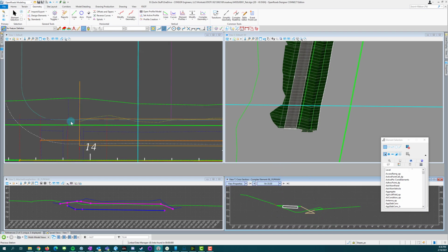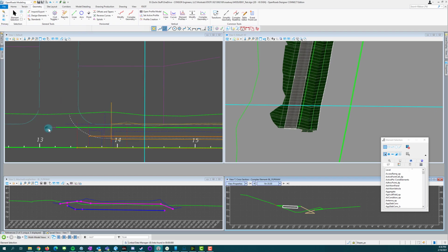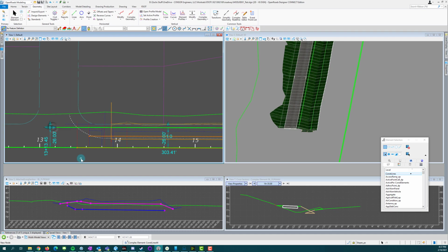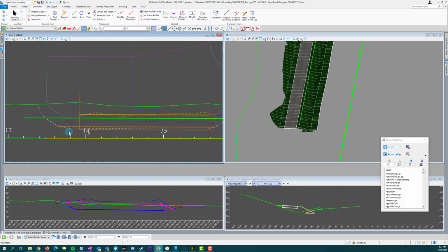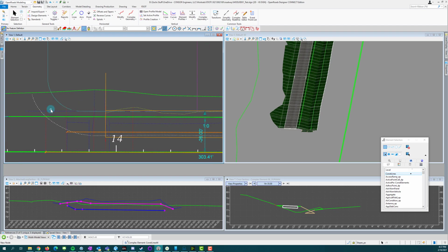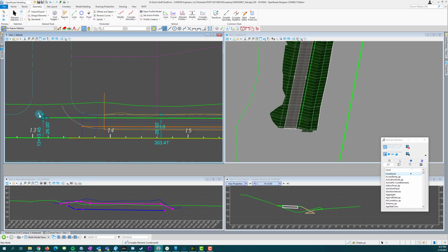I guess another thing we could maybe look at is trying to push this back a little further. So if I move this, it's going to affect the profile, because now it's not going to be taking the point that is at 26 foot offset. It's going to be taking the point that's at 27 or 28 foot offset. So if I change this line, I then have to go into my alignment file and allow this profile to update, and then come back in here and let the model update. So it's just really iterative, and that's kind of why this can be a little bit frustrating.